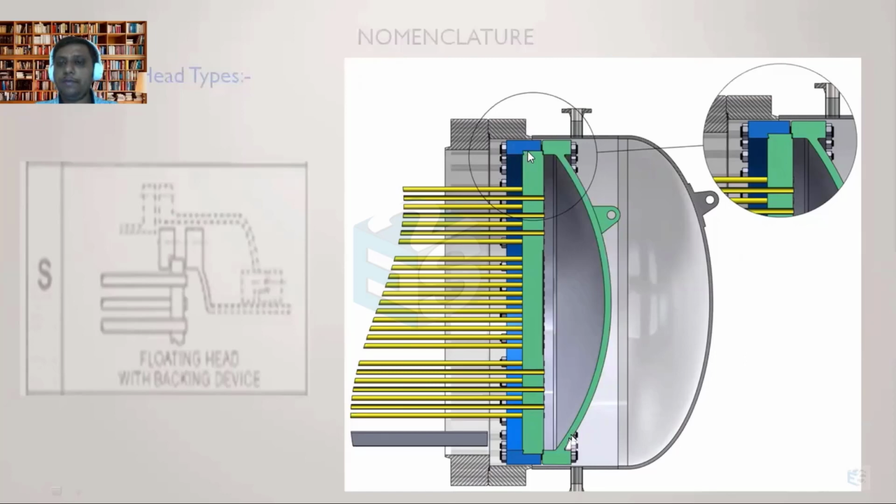that this tube sheet has an outside diameter lesser than the shell ID, that is the main shell ID. And the main shell is provided with a flange joint over here. So one flange will have an ID equal to the shell ID, and another flange will have an ID which is more than this shell ID. Why so? Because it has to accommodate this floating head and this split ring. These are bolted constructions, so the PCD and OD of these flanges will be much more than the tube sheet OD. To incorporate that, this side shell flange will have a higher diameter than this side, and